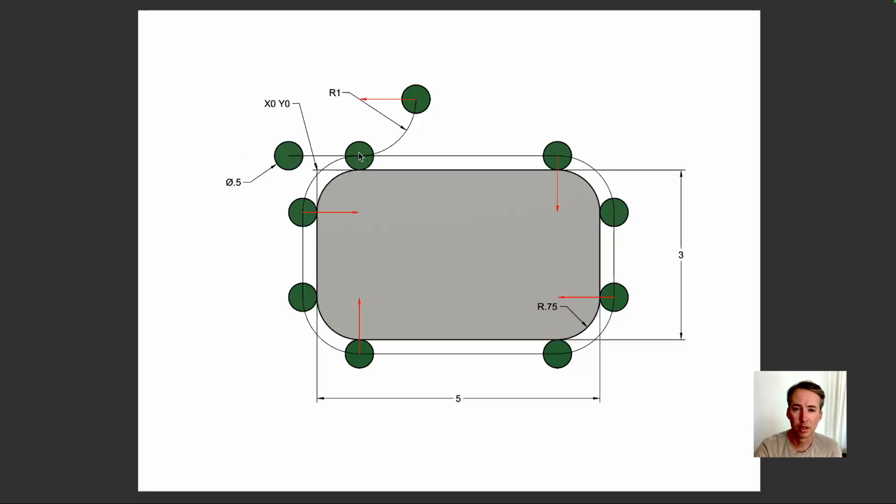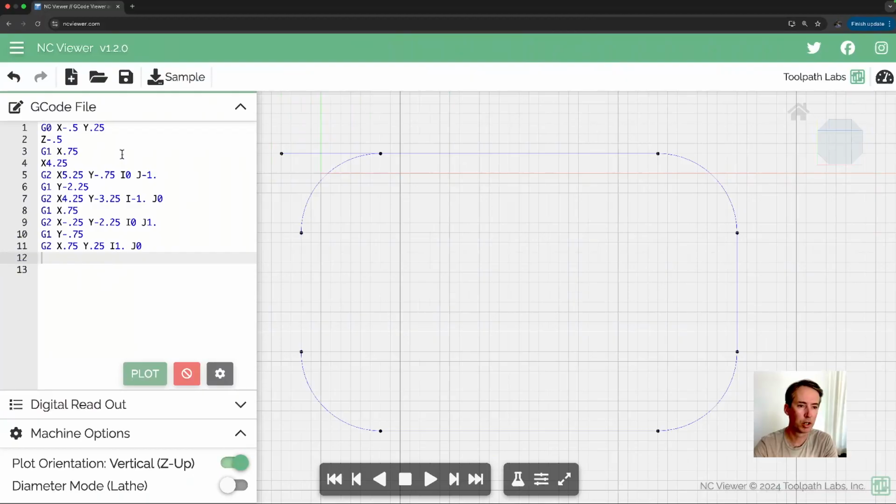let's first look at this. This is a counterclockwise arc. This is our first G3. It works just like G2, but now we're using G3. And we have an X, so we're moving 1 inch positive in X, so that should be 1.75. And then Y, 1.25. So I'm just adding 1 inch to both these numbers we had above.